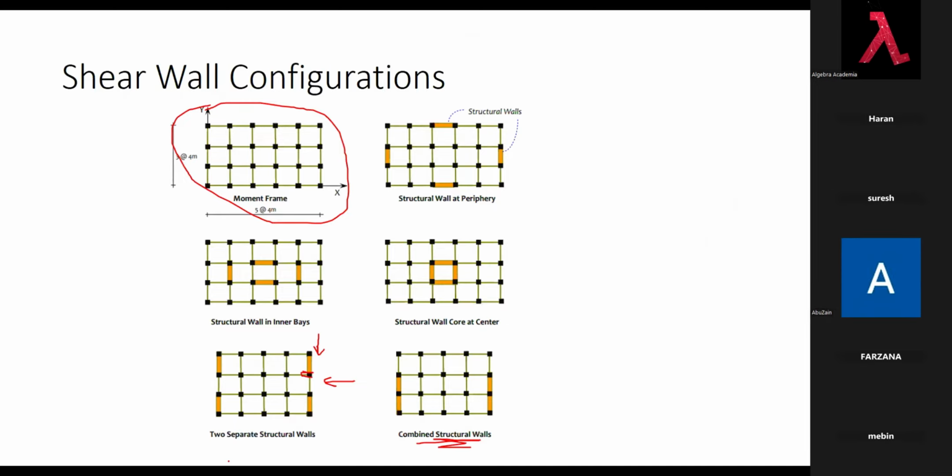So which one will we choose? This is also again a question. Which one is perfect? All are the same shear wall. From analysis we get a base shear value, so for the base shear value in the x-axis or y-axis, we can choose. Now here, which one will govern the location depends upon the torsional, like mass irregularity and stiffness irregularity, as we call it. Now in this, another thing you can see, all of these are symmetrically placed in terms of stiffness. Which one is better? So again we need to do some research and then come to a conclusion.